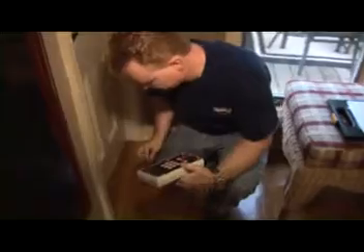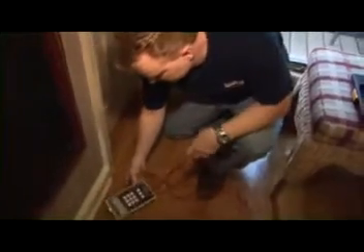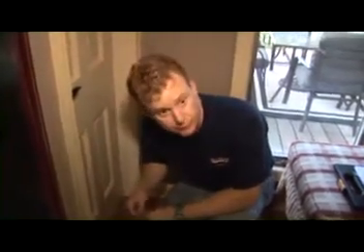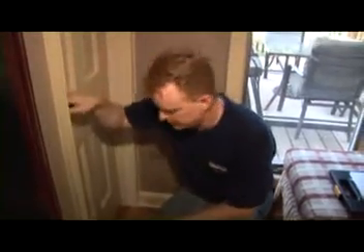Okay, so now I'm going to test while the blower door is running with my manometer to see if there's any unwanted airflow in this bathroom here. Now again, we should be getting a reading of 0 pascals if there isn't a lot of airflow from the outside to the inside. Any number over 0 means there's some kind of air infiltration going on.